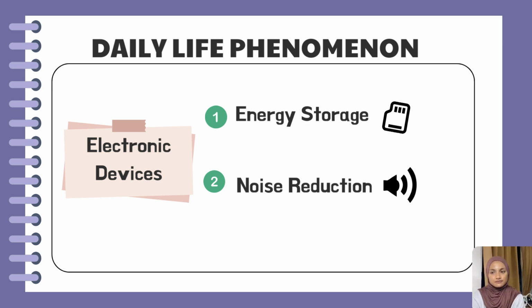Second, noise reduction. Capacitors aid in reducing electrical noise in electronic devices, ensuring proper functionality. They act as decoupling capacitors, diverting high-frequency noise away from sensitive components through a low-impedance path. By absorbing and dissipating noise, capacitors help maintain signal integrity and minimize electromagnetic interference.